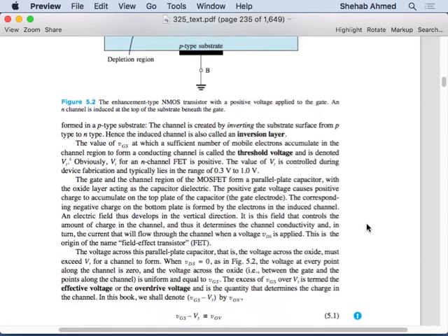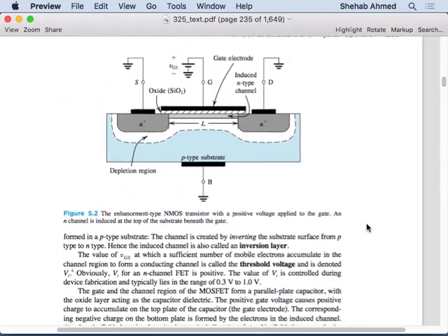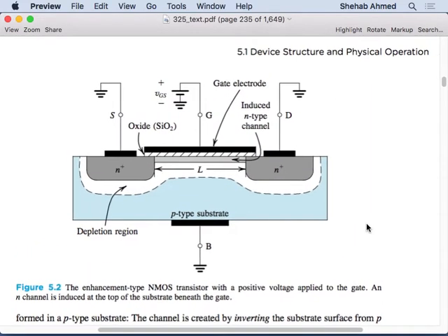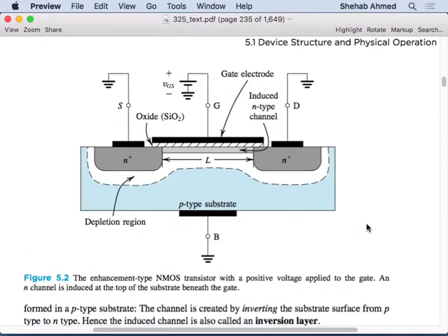Okay, now let's formalize what we're talking about into a set of equations. And again, the objective is what, guys? I've created this gate to source voltage. We said that the gate to source voltage will have a value, but the current is almost zero, right? Because it's a capacitor. I will charge it to a voltage, and that's it. There is no current being consumed.